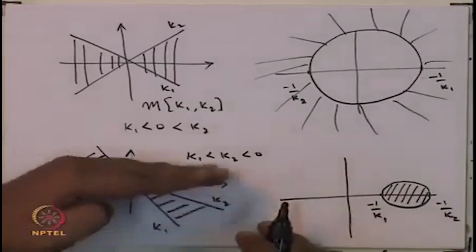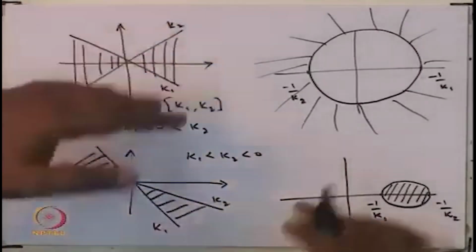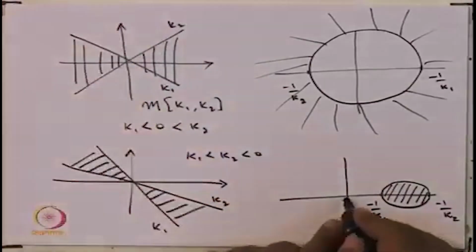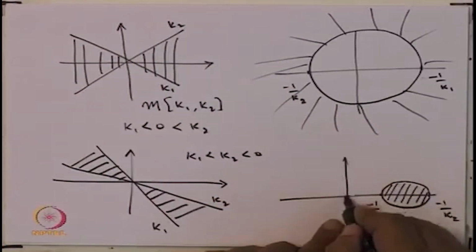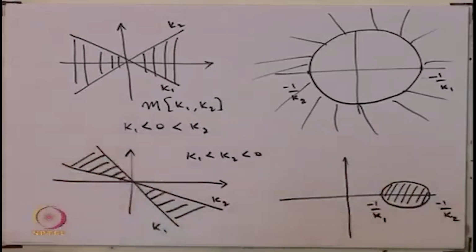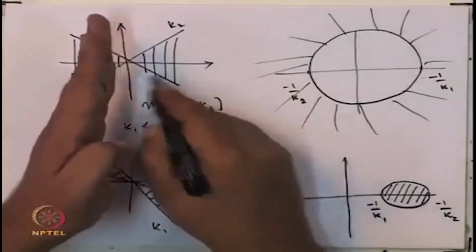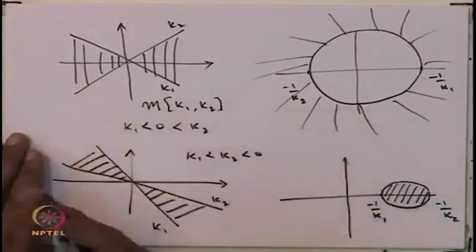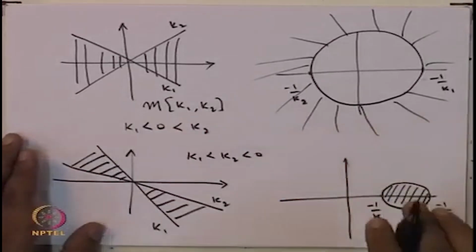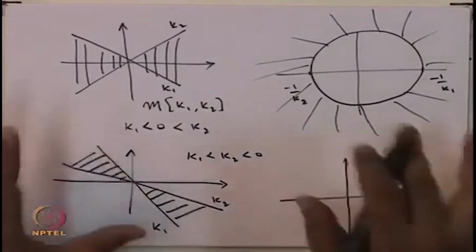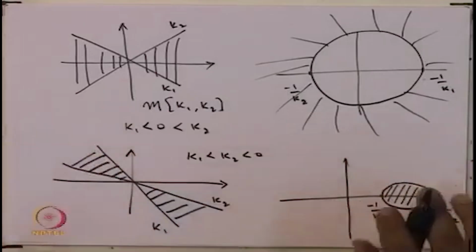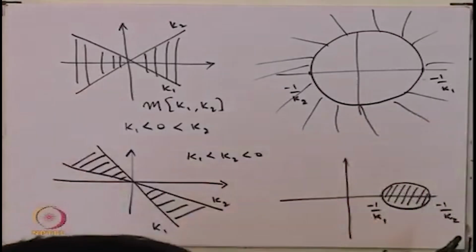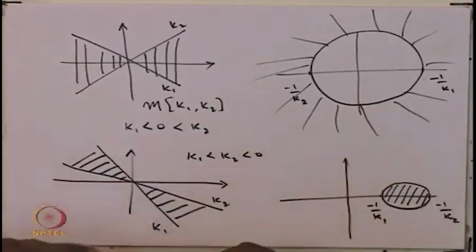Of course, K2 could be made equal to 0, or K1 could be made equal to 0, and you have these special cases. K2 could go off to infinity, which means that in the original axis it will hit 0. Yeah, the circle will hit 0, and the special case of 0 infinity sector being the left half is the forbidden part and the right half is the nice part. Okay, so that gives the complete sort of interpretation for the various aspects of the circle criterion.